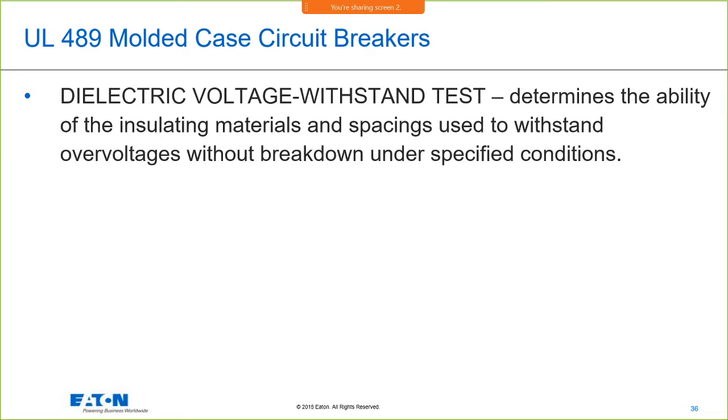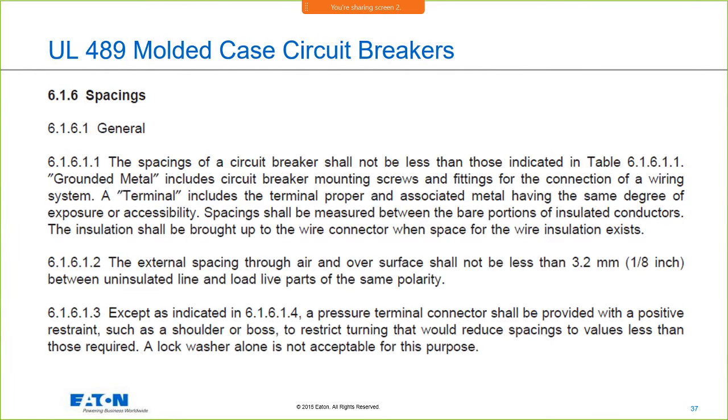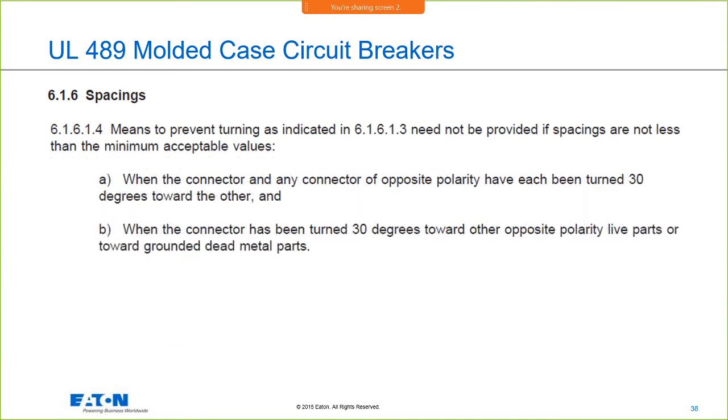We have testing, and we do dielectric tests, and we have requirements for spacings between those breakers to give us enough space so that we don't have tracking, say from lug to terminal, and the standards go into specifics on what those spacings need to be.